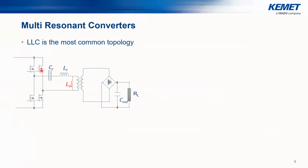The most common one is the LLC, and here we are seeing the topology of these converters, where we have added LM in parallel with the transformer. This LM is in reality part of the transformer, so there is no additional part added to the circuit. Sometimes LR is also dimensioned to be taken into account when designing the transformer, and in some cases it is different: it is considered outside, as a separate component from the transformer. It depends on the power levels and the configuration of the final power converter.